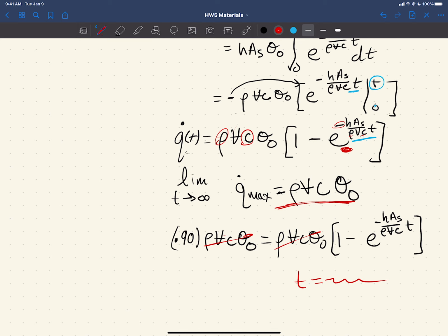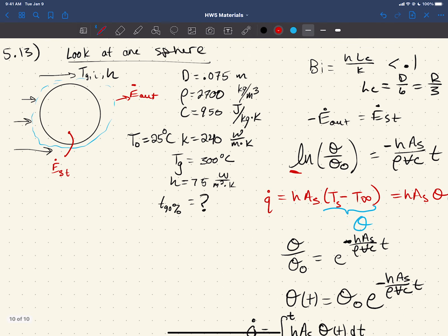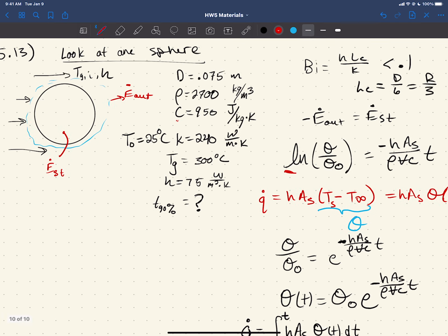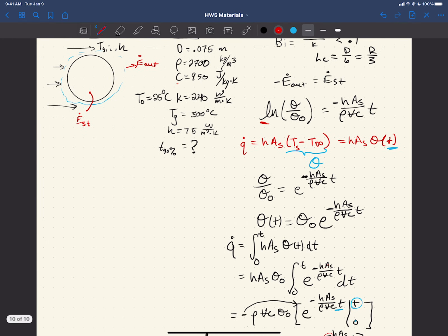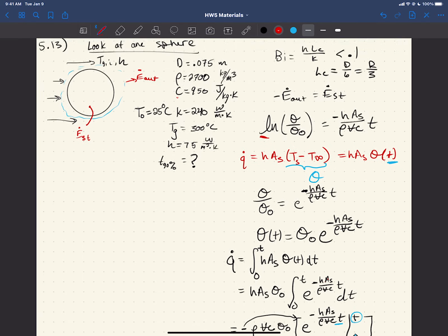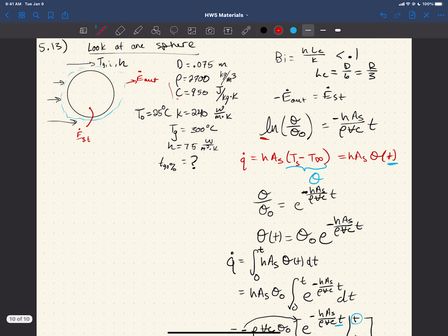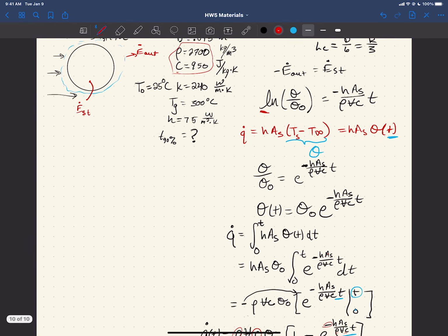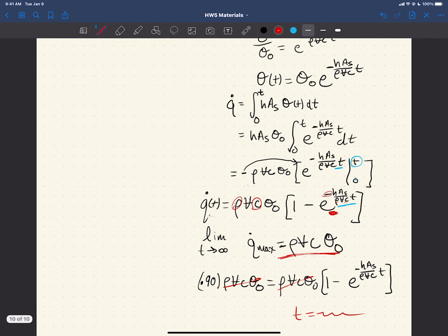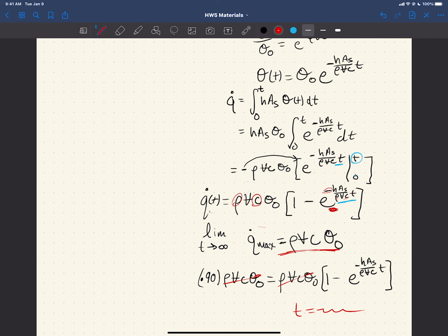And so you can go and look it up. And if you look at it, the rho C of aluminum is less than the rho C of copper. And remember, rho C is just density times specific heat, and you can find that in table A1 or something like that. And so you can compare the values that were given here, because these ones that are given up here are for aluminum. You can compare that multiplication of that combination to that of copper, and if the copper's higher, then the copper's better.